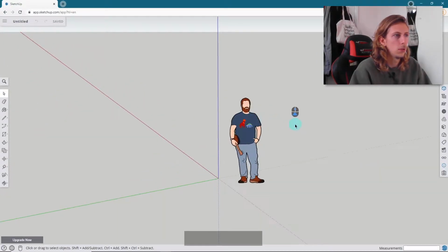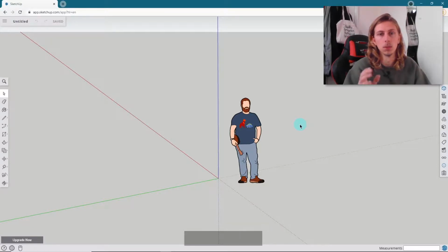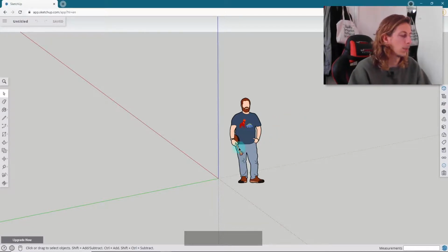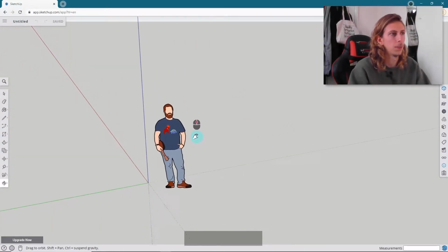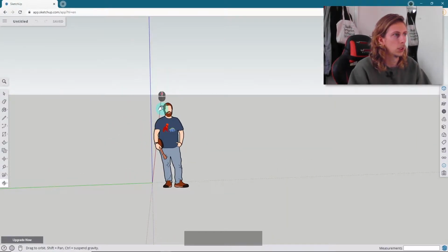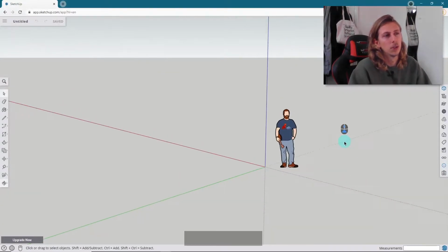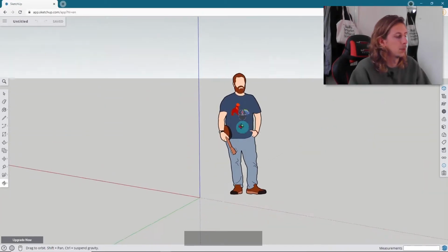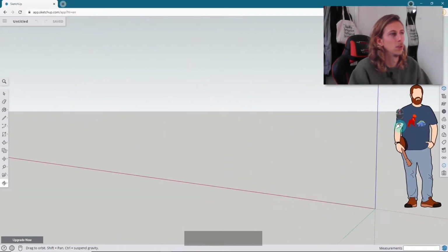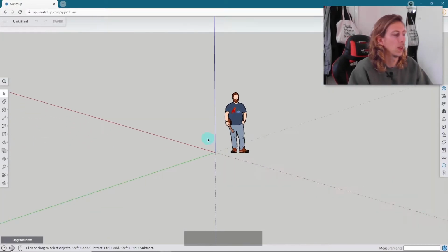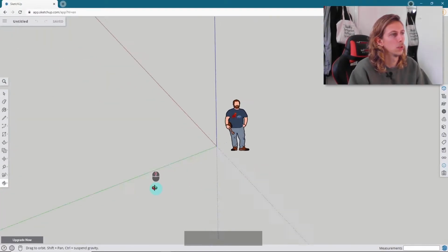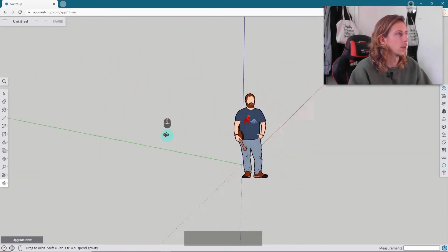What you can also do is if you click down your mouse wheel and then click your first mouse button, you can pan, but because my mouse changes the sensitivity when I do that, which is really annoying, I can't do that. But what I've been doing instead is pressing the shift key. So as I'm clicking my mouse, I press the shift key and I can pan. And this is actually a very useful tool that I end up using quite a lot. I remember when I first started, I was just scrolling in and out, but there will come times when you almost want to look around objects, so you use the pan tool to do that. And that's just the shift key on your keyboard. So that's the basics of how to move around within SketchUp.